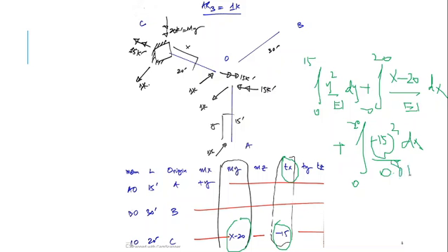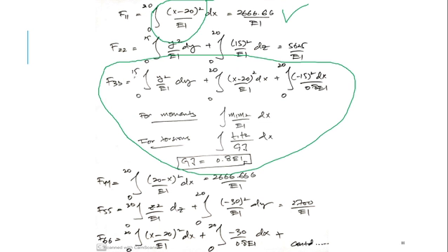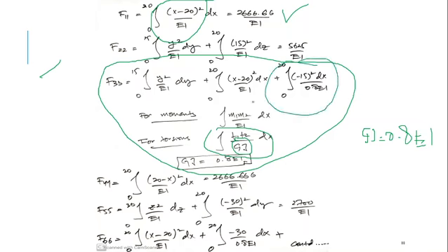Instead of EI, you will divide it by EI, because actually in the formula of torsion, when T1 multiplies with T2, it should be divided by GJ, and GJ can be taken as 0.8 EI. So you should be very careful while multiplying the torsions. When you are going to multiply the torsion section, you will divide it by 0.8 EI.